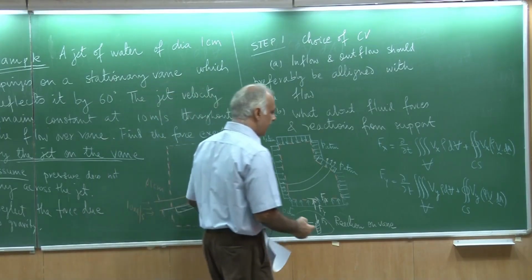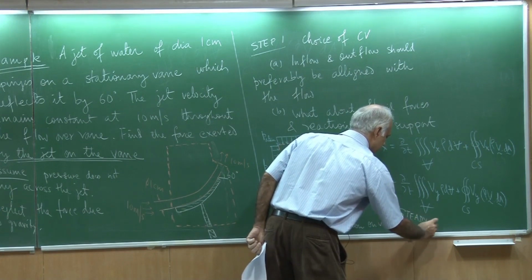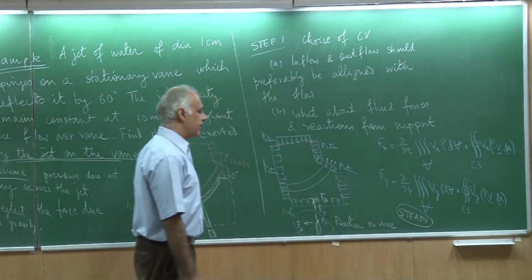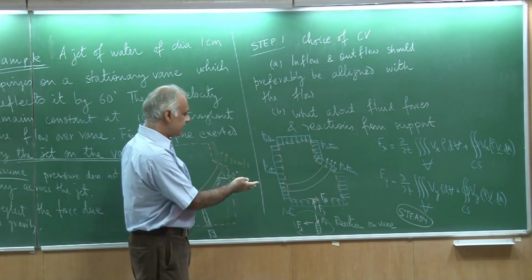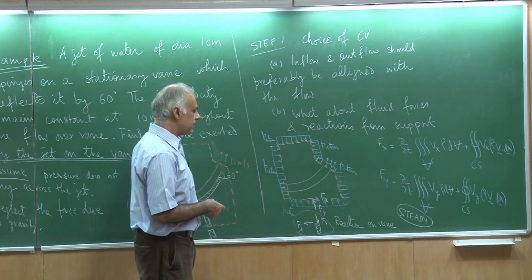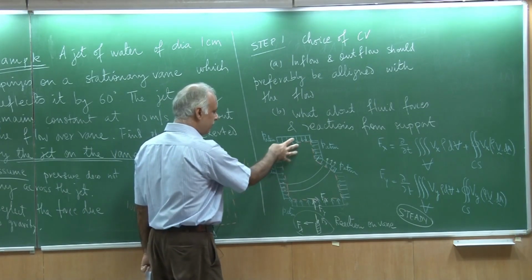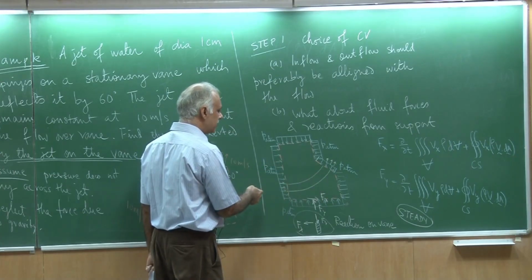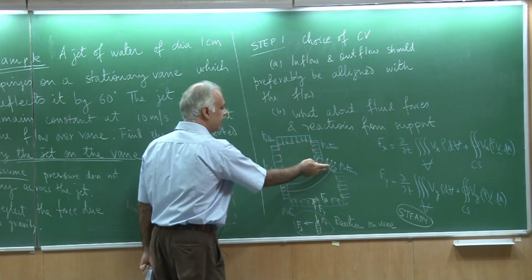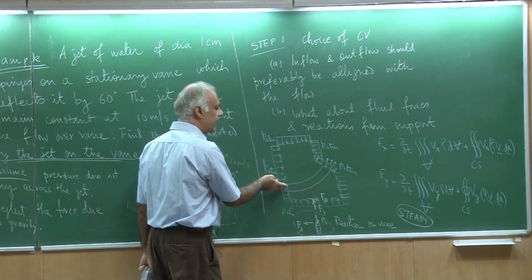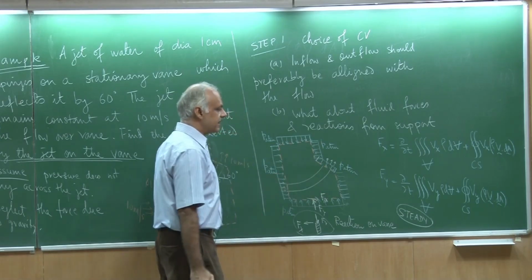We already know that the flow is steady. What that means is, if I stand here as an observer and this is a fixed control volume, then nothing changes in this control volume. So if I concentrate on the momentum inside the control volume, I always see the same fluid coming in at the same velocity, leaving at the same velocity, and really nothing much is changing.